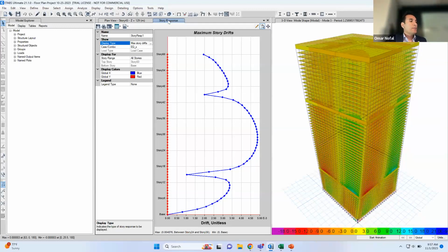So shear lag is basically the reaction in the columns, because you have a column here and a column there and a column there, and this building having an earthquake and keeps bending. So there is tension in this side of the building and compression in the other side, or vice versa. What we want to do is know what the compression is in each column.